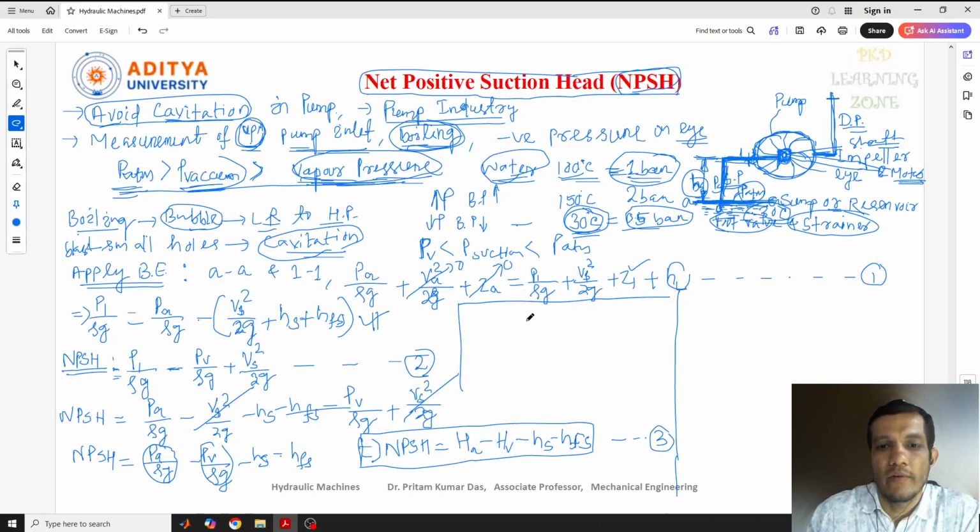So the pressure equation we have in the hydraulic law, we found P equal to rho G H, pressure. Now here rho is density, G is the gravity value, and H is head or height. When you calculate the head, H equals P by rho G.